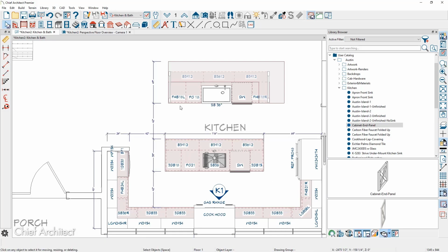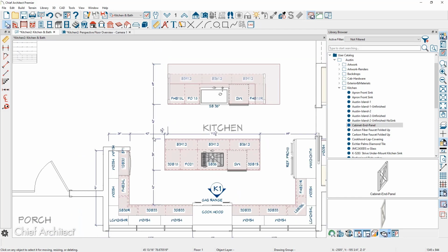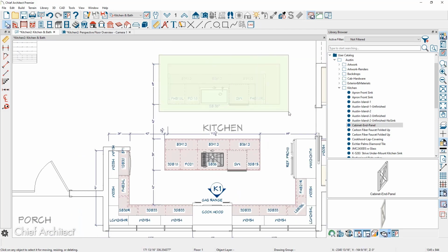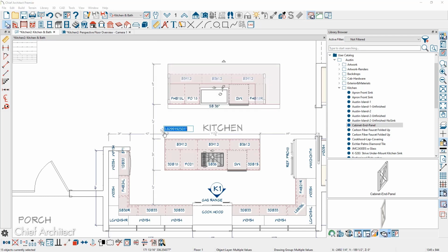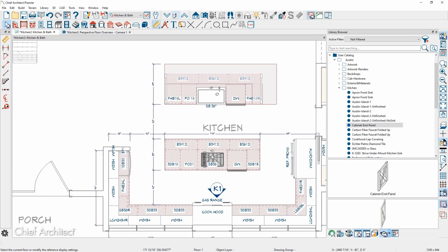To position the other island in location, let's go ahead and click on the extra diamond. I'm going to come over here, pick up the diamond. You see that it's 3 7/8 off. Click and drag the marquee, come over to the dimension, and I'm going to enter in 0. So the two edges of those will be exactly flush.